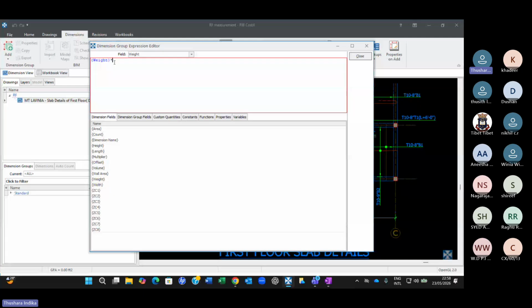Linear meter weight, if you go to Google, is 0.617, but now we are going to measure in feet, correct? So the multiplication factor is different. So 0.617 is for meter, divided by 3.3 you get kilograms per feet, and if you go to the internet, you will find it anyway. So you have to multiply it by 0.1869. So this is the kilograms per linear feet of T10.